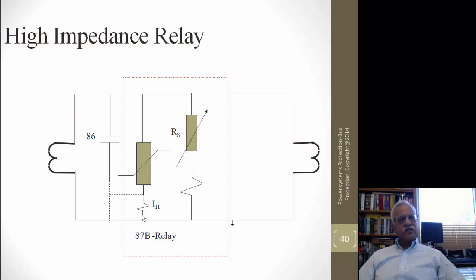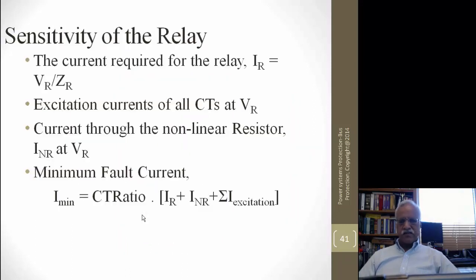As I mentioned in the instrument transformers, CTs will have 5 taps as per ANSI standards in the United States. We have to look at other standards in different parts of the world to see how many taps are available in the CT. The reason why we use full tap is we want to use the full capability of the CT. If it is C800 at 2000:5, you try to use 2000:5 so that you can get C800 capability. If you use the tap of 1000:5, then your C800 becomes C400, as we discussed in the instrument transformers.